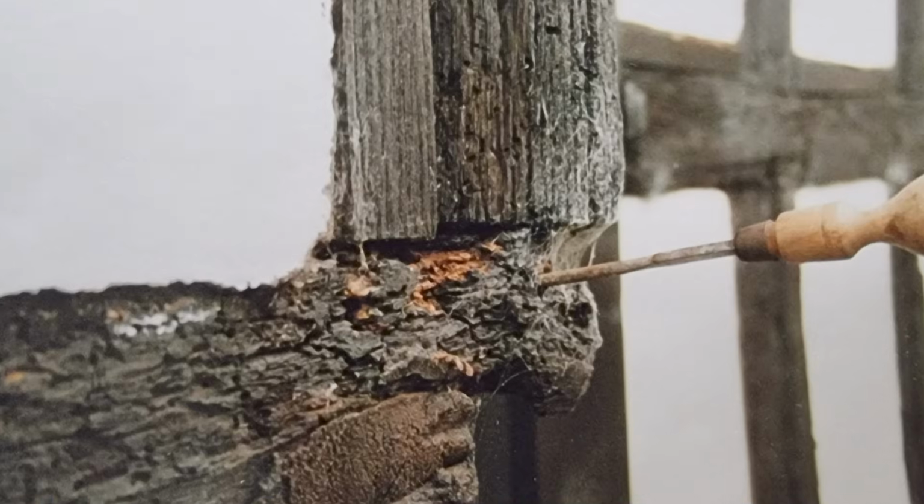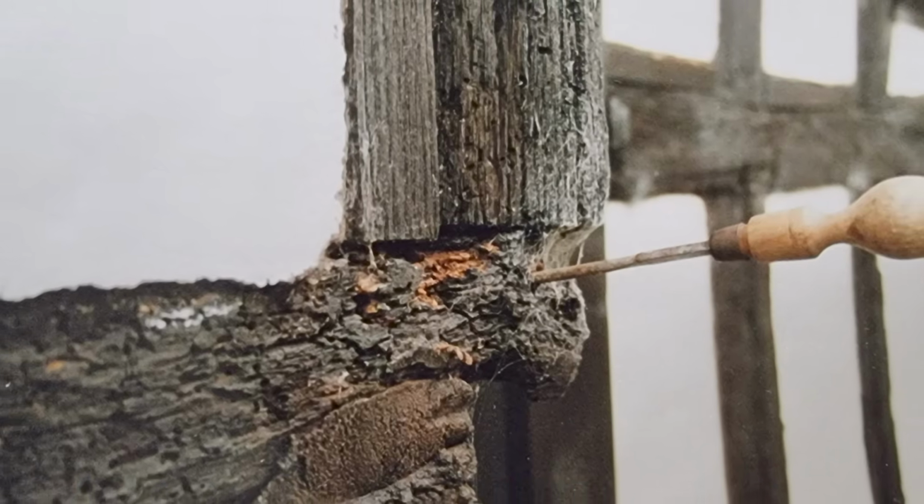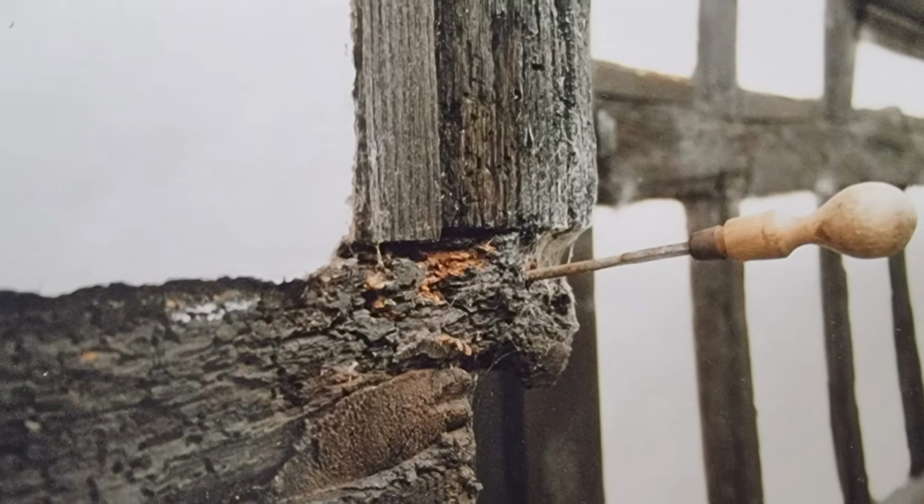And sometimes in larger timbers, where there clearly is a problem, I might take out a bradawl or a pointed screwdriver, one that's been sharpened slightly, and just push it in to see a little bit further how far it will go in. So there are ways and means that are not too destructive. And if you're careful, you won't see where you've done that, but that's a way of doing it.